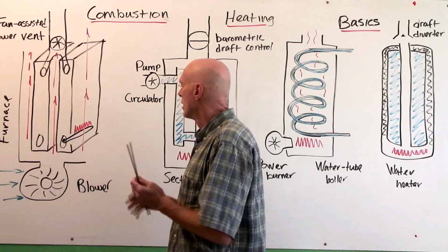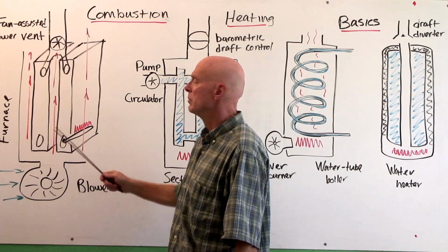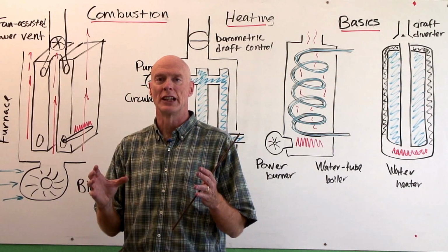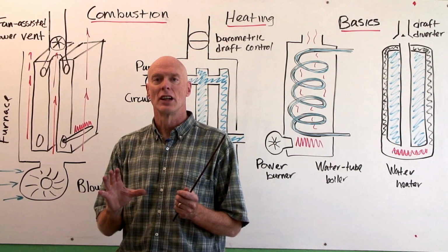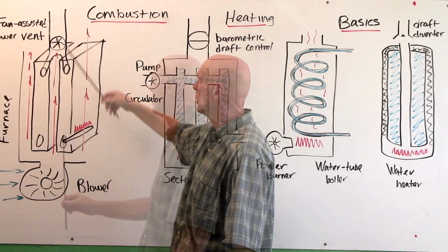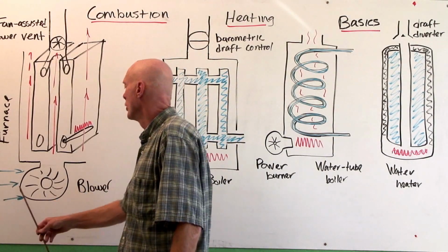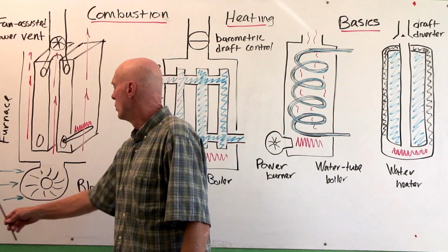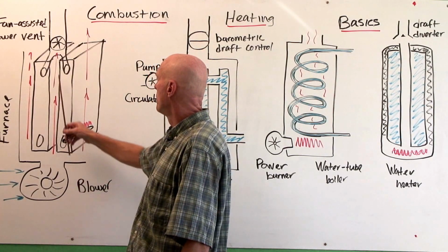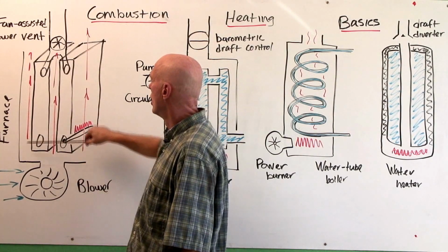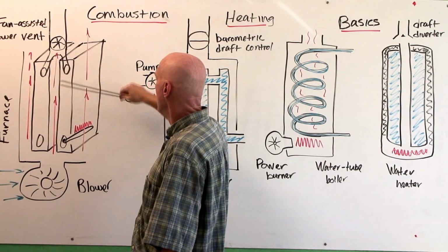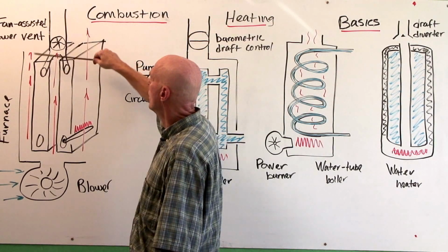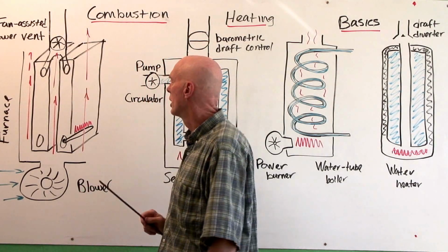So the heat exchanger is part of a system inside the heating device that takes the heat from the flame and from the combustion gases, but directs the exhaust gases into the flue. So here the return air from the house or from the room, in the case that this would be a space heater, would go into the fan and be blown up near the metal heat exchanger, right alongside of the heat exchanger, and the air would pick up the heat from the heat exchanger and be either discharged into the room or discharged into the supply ductwork.